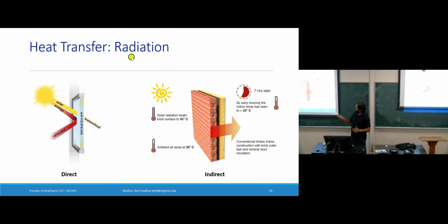However, the sun is also shining directly on this wall with some flux of delta times watts per meter square. So if we know the area of the wall, we can compute how much solar direct radiation is going to change the temperature of this wall. And once this outside temperature changes, there's going to be conductive heat flow through the wall, which will change the inside surface temperature of the wall. Right?